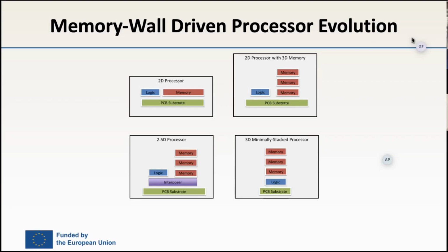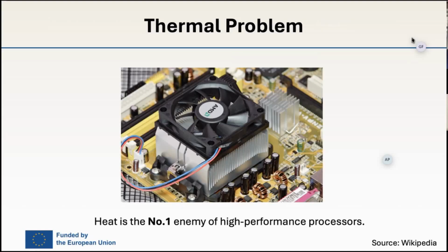And the final piece of the puzzle that was left to do was to stack the memory directly on top of the logic, which allows for 3D interconnect connections between the memory and the logic, allowing for a massive increase in the bandwidth and very low latency. But this came with some undesirable consequences, which basically came in terms of heat.